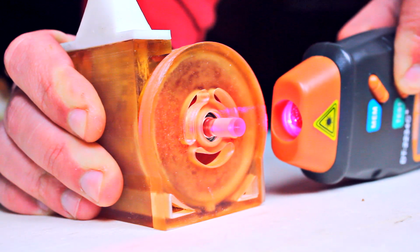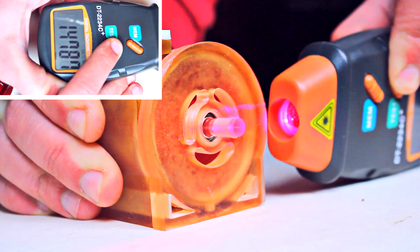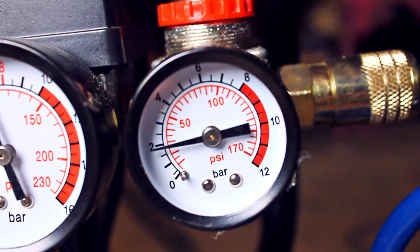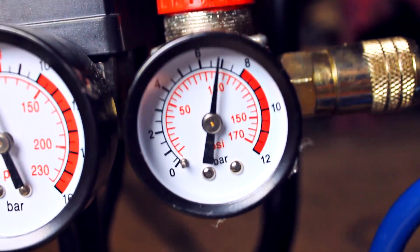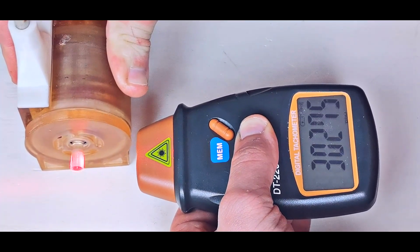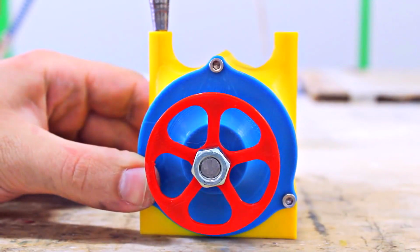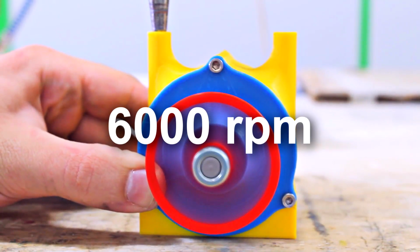I started off with the standard turbine and, using my tachometer, I measured about 15,000 RPM. Then I realized I had the compressor on 2 bars of pressure. I cranked that up to 8 bars and I tested again. Reached a speed of 31,000 RPM, which basically beats the record of my first Tesla turbine by 6,000 RPM.